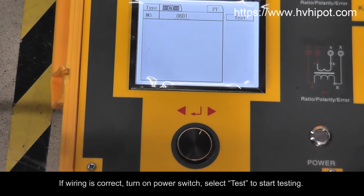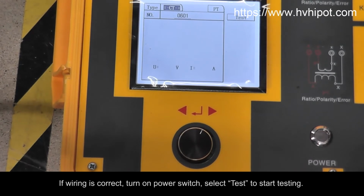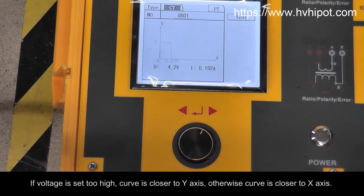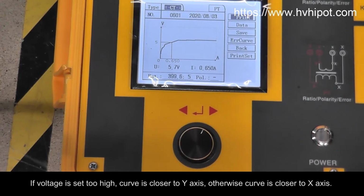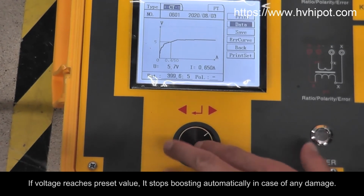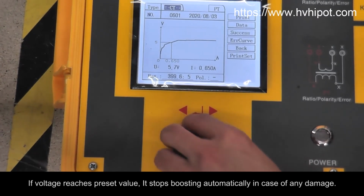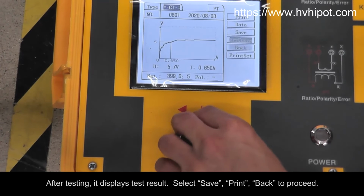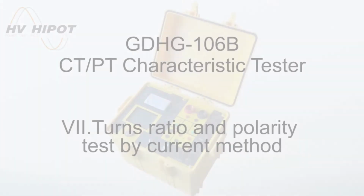If wiring is correct, turn on power switch, select test to start testing. If voltage is set too high, curve is closer to y-axis, otherwise curve is closer to x-axis. If voltage reaches preset value, it stops boosting automatically in case of any damage. After testing, it displays test result. Select Save Print, back to proceed.